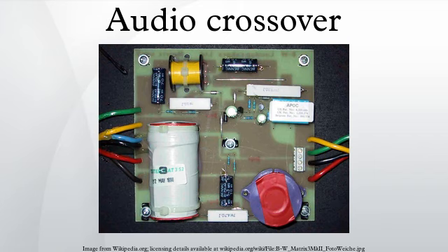Higher-order passive crossovers giving acoustic slopes higher than fourth-order are not common because of cost and complexity. Filters of up to 96 dB per octave are available in active crossovers and loudspeaker management systems. Mixed-order crossovers can also be constructed with mixed-order filters, for example, a second-order low-pass combined with a third-order high-pass.